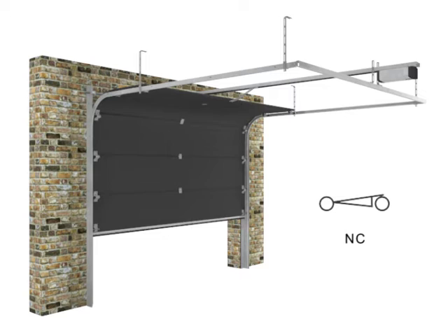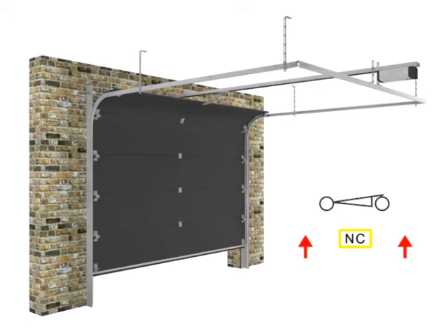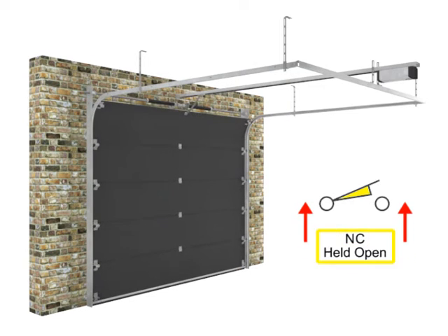When opposing pressure is applied to the normally closed limit switch, current to the motor is interrupted, stopping the motor and bringing the door to rest in a down position. In this way, the limit switch defines the limit of movement of an object.